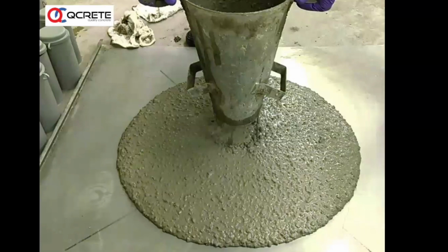Now we have moved to what is called self-compacting concrete. All of you may be aware that self-compacting concrete was first introduced by Okamura of Japan in 1986, and from 1986, especially through 1990 onwards, 2000 to 2010, it has moved well and become popular. So self-compacting concrete is a concrete which consolidates by itself. There is no vibration required. It levels by itself just like water, and you can see how the flow takes place. This is called a flow test.